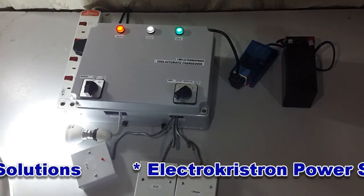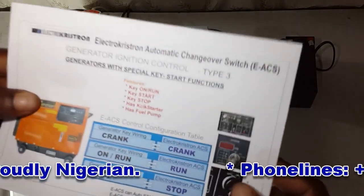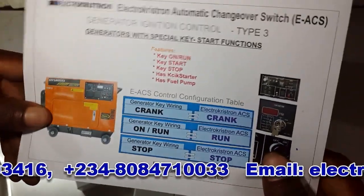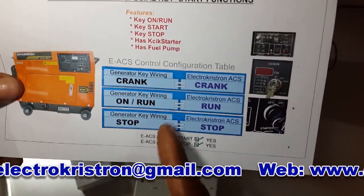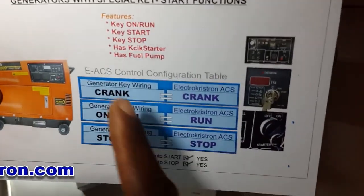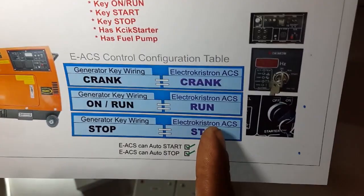Now, the third type of generator we want to talk about is generators with special key start functions. There are certain generators that actually require three different control lines to be connected for that gen to work properly with the automatic changeover system. You need to connect both the crank, the run lines, and then of course the stop lines.